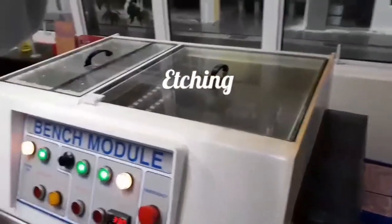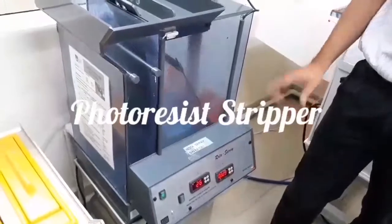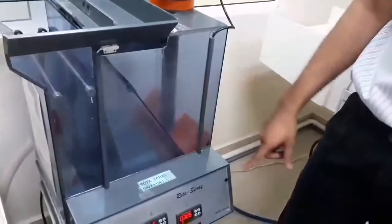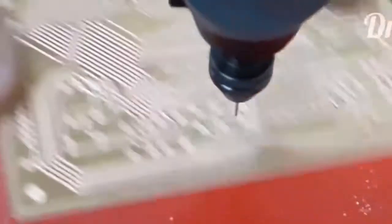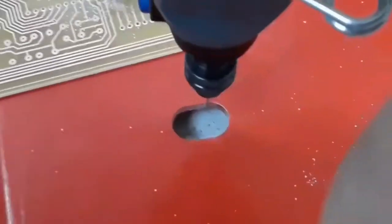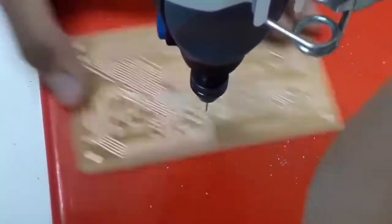Next is the etching process. The board is placed in an etcher which washes it with warm ferric chloride. All the photoresist from the etched circuit board will be removed and the copper that makes the circuit on the board is removed. For the drilling process, holes are drilled one by one using a suitable drill bit shown by the instructor. Holes are made on the PCB to insert the components before soldering it.